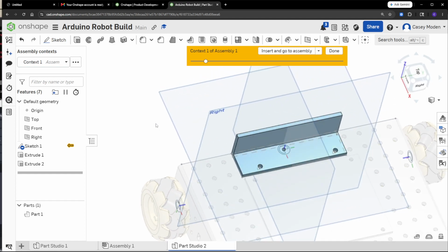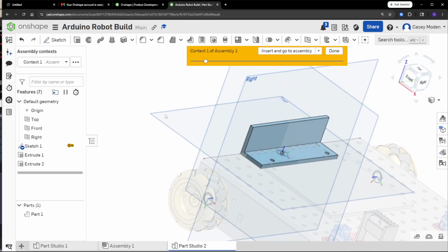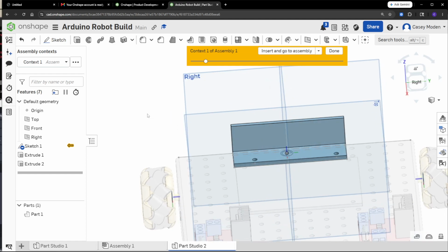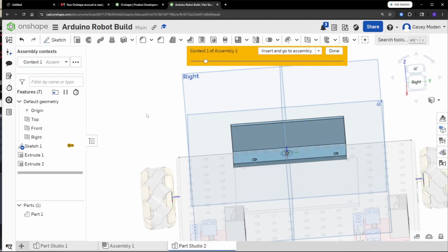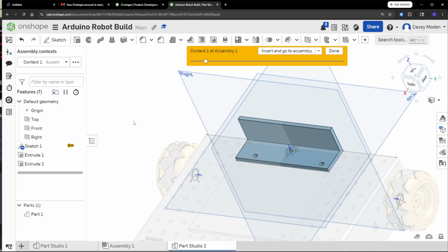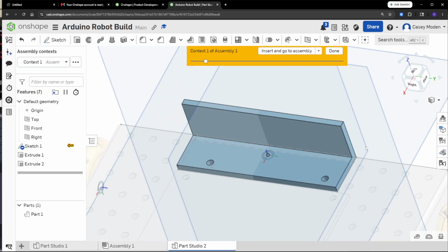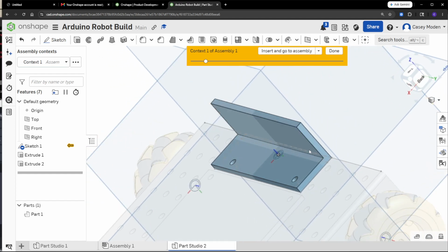We have our first piece. Before we go too much further, before we add the front text in here, this is what you would be doing when building your robot. You might want to design some geometry like this. One really critical thing: you typically don't want to have very sharp edges in your design. When you have sharp edges, if there's force applied, all the force tends to meet at this point and causes breakages at that point.